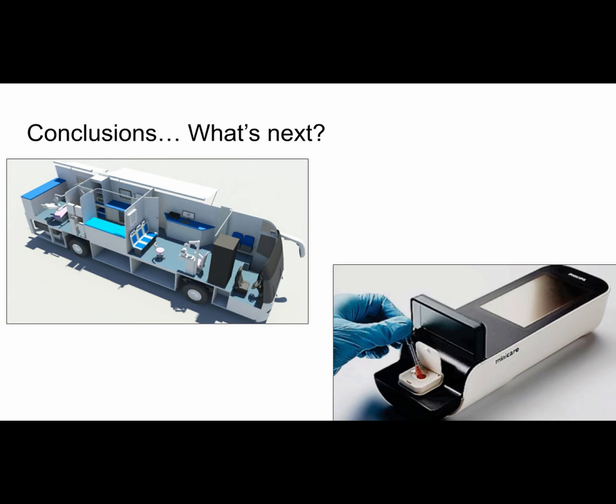It should also be noted that this improvement or reduction in the required voltage can be increased by, as previously mentioned, reducing the width of the elliptical obstacles in our insulating posts of the microfluidic channel. However, this can also prove to be an obstacle in manufacturing, especially when we're talking about these remote laboratories or off-site laboratories and point-of-care systems.